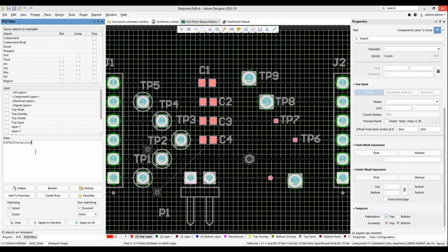Now, can we get around the whole test manager thing? And the answer is yes. You can do that. Number one, again, if you have your library set up as to what things are test points and what things aren't test points, then some of that's going to be driven by having your rules in terms of the usage and, more importantly, their placements. So you can use the rules to make sure that they're properly placed. But the libraries can tell you which ones are test points and which ones are not test points.